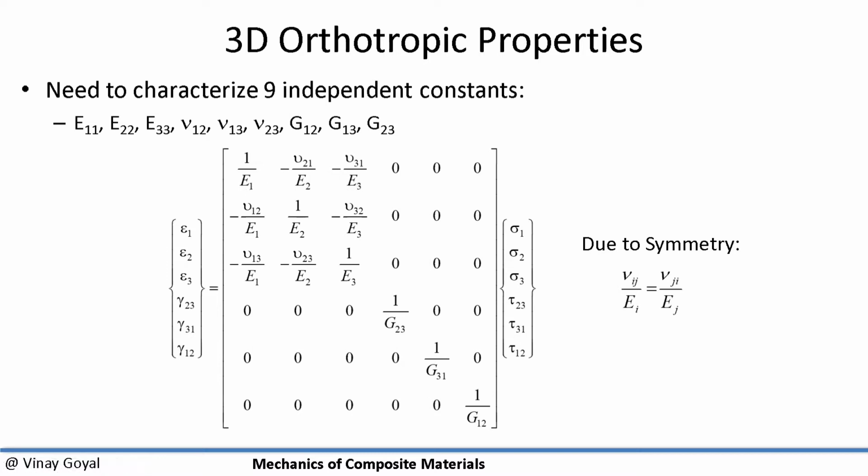And then when I look at the Poisson ratio, we need to fully understand what it really means. You're basically loading in one direction and measuring the strain, how much percentage contraction strain you have across that loading direction. So I apply a load in one direction, and I see how much percentage contraction I get in the second direction.